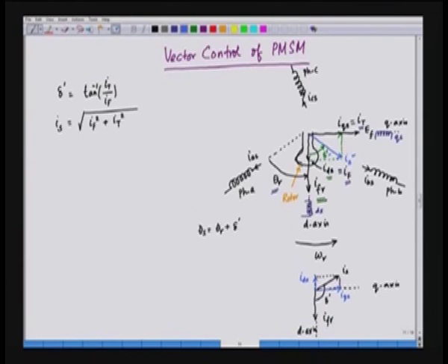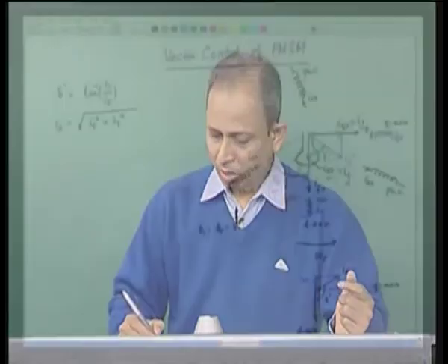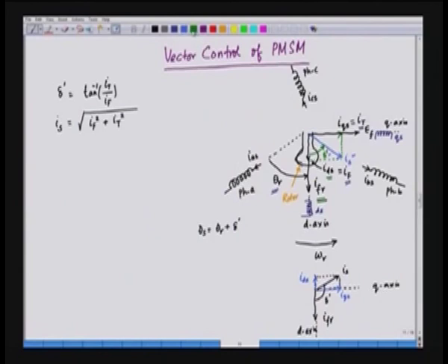So when IDS is opposing IFR, the flux is reduced, and the resultant of IF and IS is going to be low. We can find the resultant by completing this parallelogram. This is the resultant of IS and IFR, which we call Im, the magnetizing current. Im will be reduced because of negative IDS, and that is what happens in flux weakening.